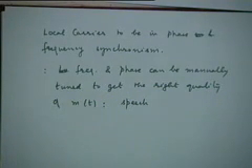You can manually do it in cos omega_c t and multiplying it also. That is what I'm saying. Theoretically it can be done, but that's a much more difficult thing to do than in this case, right? In other words, if you do some analysis, you will find that this is less sensitive to the phase and frequency errors than the other system is, right? I'm not doing that analysis here, but there a slight phase offset will completely start distorting your signal because of the multiplication with the terms cosine theta(t) and sine theta(t), right? Here it will not be as sensitive as it is in that case, right?